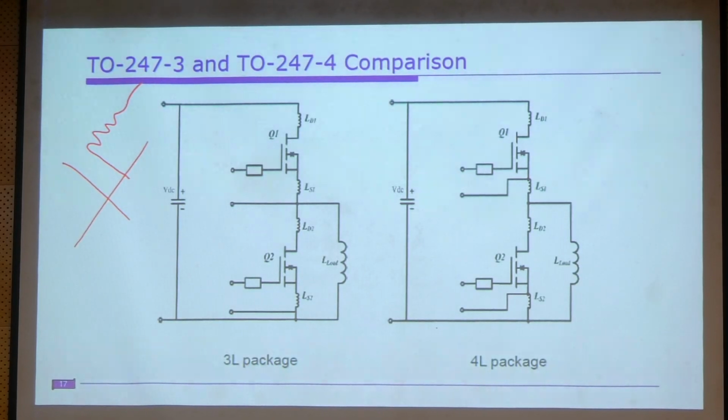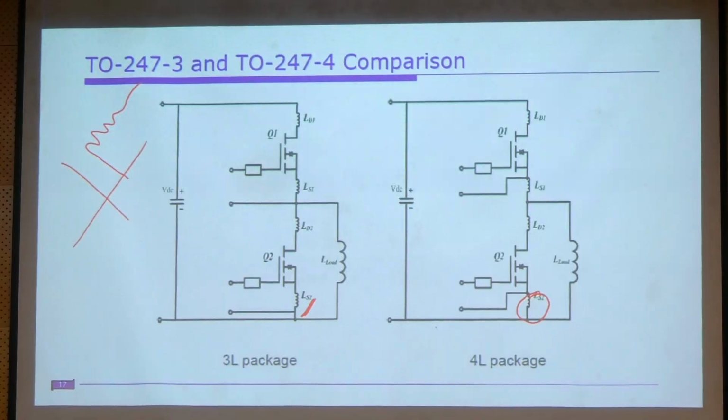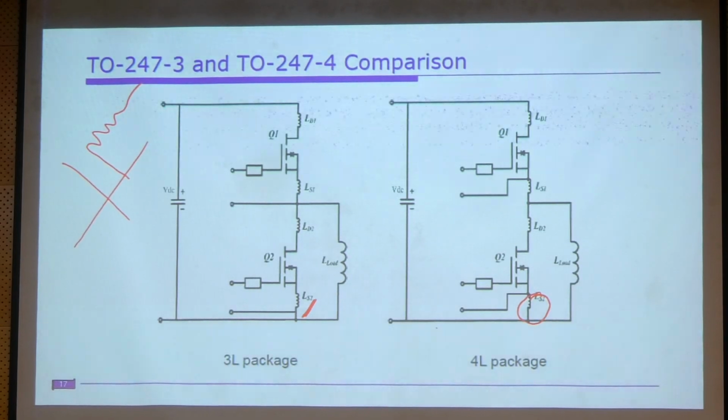We expect a sharp rising and falling edge of the pulses. If that is not happening, it means we have extra losses. Understood? Here, this inductance is also included in the gate driver circuit, which means the gate pulses themselves are distorted. To avoid that, we connect this one inside, so this is bypassed here, and it does not come directly into the load path.